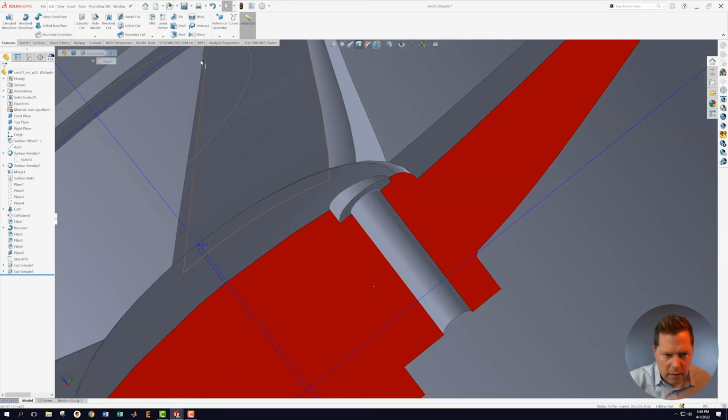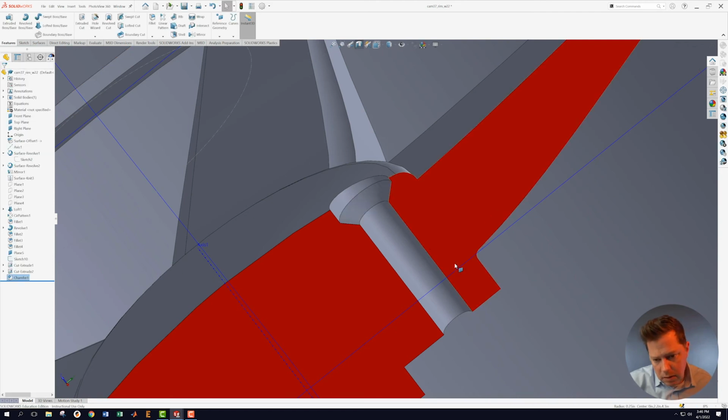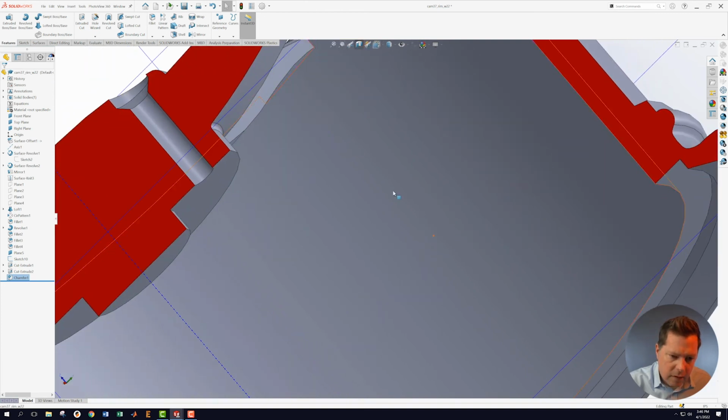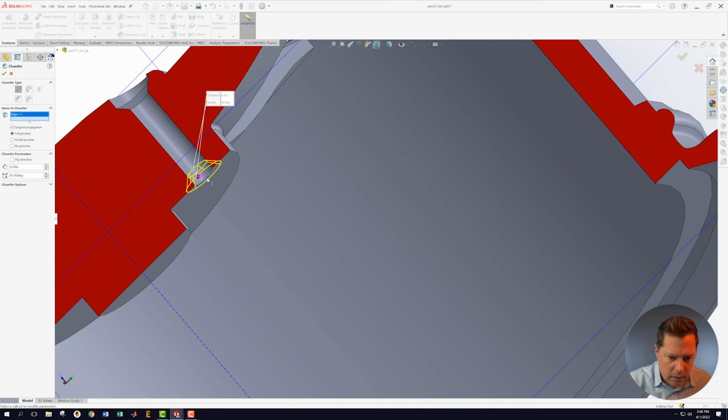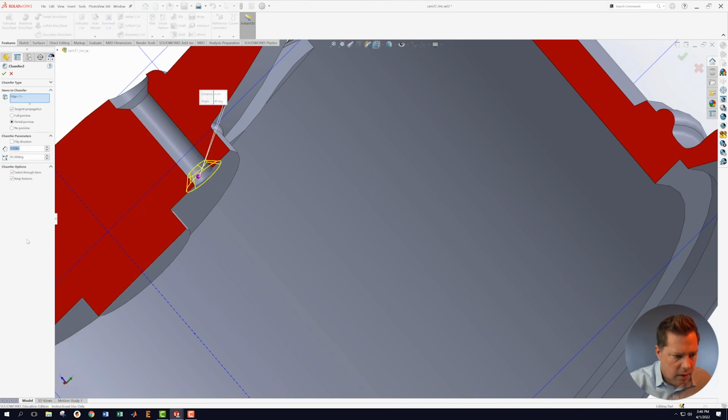I'm going to grab this, come up here into chamfer. Yeah, right. Okay, so I'm going to be 0.2 on this. Is it going to work? Yes, that's right. And it looks like there's another chamfer on the bottom. So let's go add in that other chamfer, which is here. That one is 0.1. That did not look like 0.1. Let's go change that.